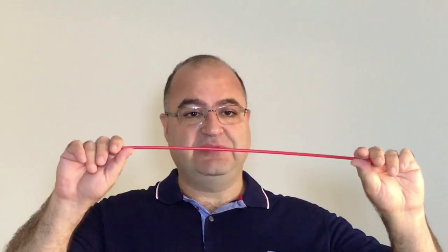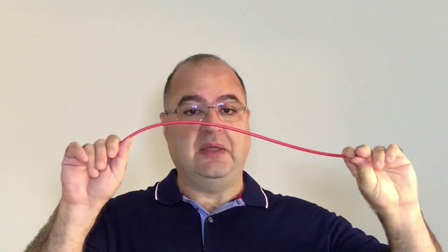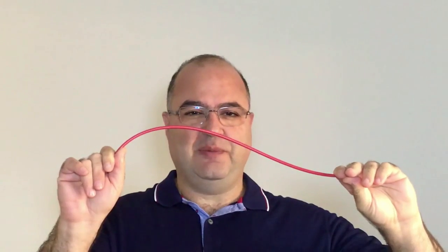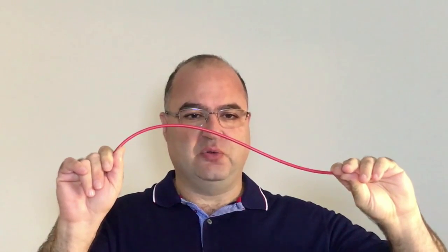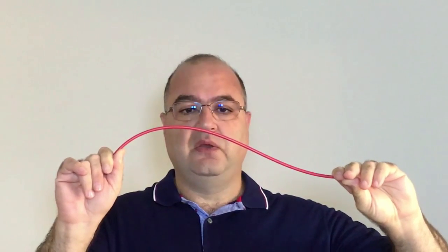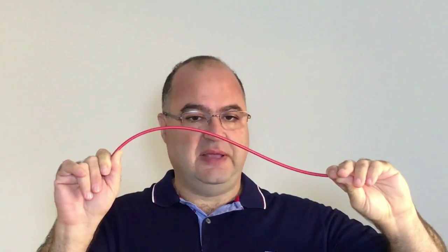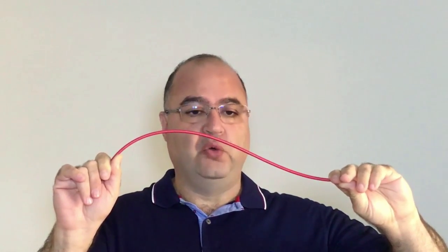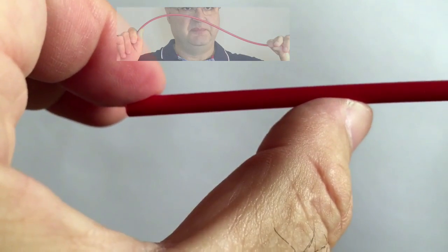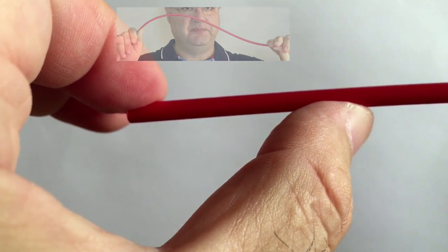The next simple configuration is a beam with a moment applied at one end and a fixed support at the other. This straw can again demonstrate the deformed shape. This shape would be about the same as for a steel, concrete, or wood beam, but of course, again, with much smaller deformations. We could use a digital camera and software to calculate optical flow to capture this deformation in real beams. Again, we apply the bending moment in the same way as before.